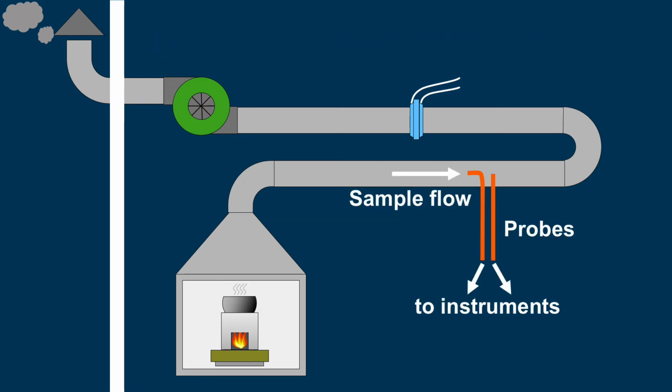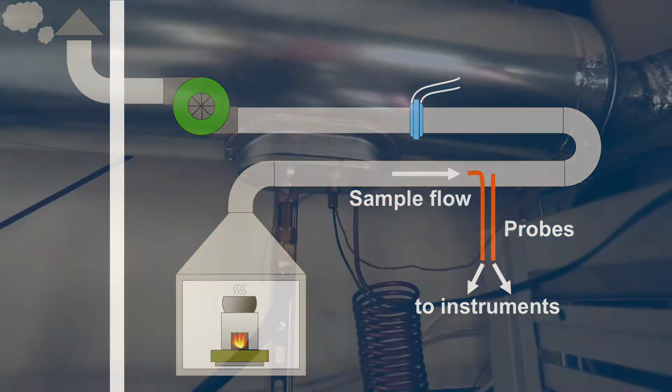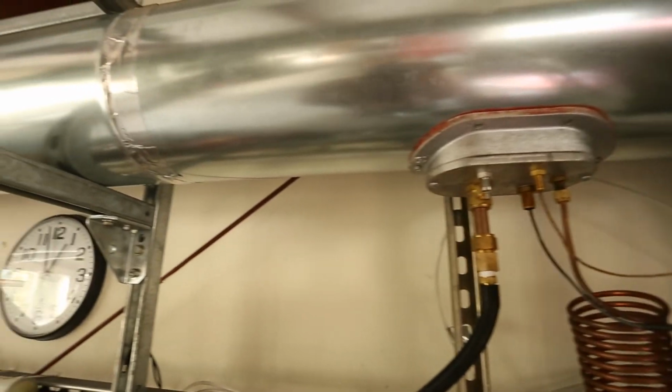While the volumetric flow rate should be low enough to prevent draft, it should also be high enough to ensure complete mixing of the emissions and room air. This is because the emissions are sampled from the duct, and we want to ensure that a sample taken from the duct is fully mixed and not biased towards polluted emissions or cleaner room air. Sample probes for emissions instruments, such as gas analyzers and gravimetric filters, are mounted inside the duct using an access panel.